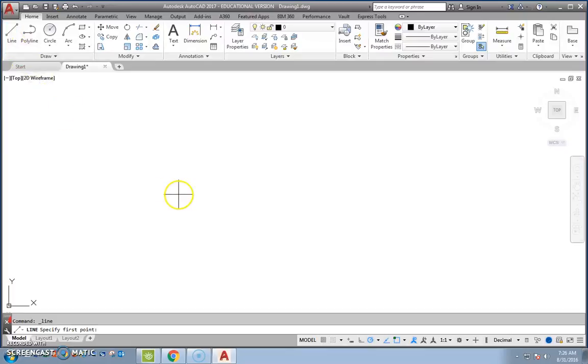Since we're just mostly going to be messing with lines, you can go up and click the line button, and then you can just continue from your worksheet. We always talked about how the first point was 2, 1. You can see here I just typed 2, 1 and it automatically inserted it into my command line. You don't actually have to click inside the command line to activate it.